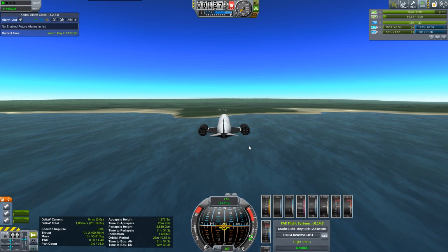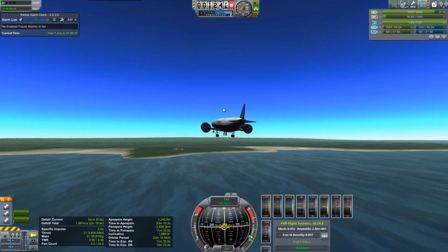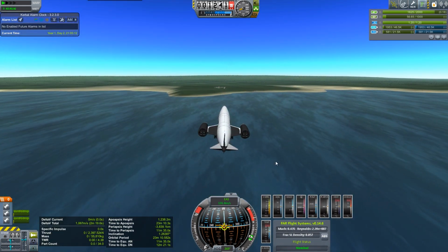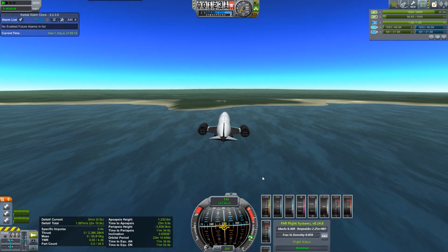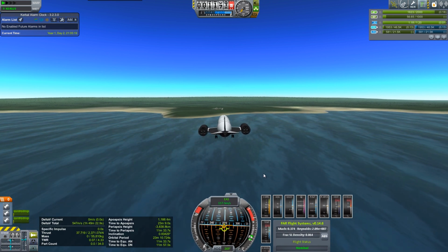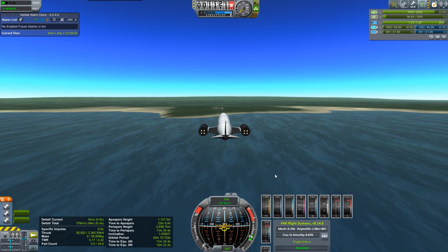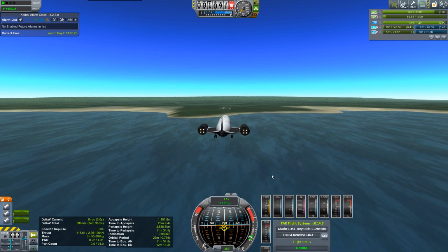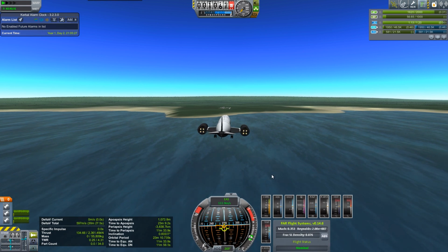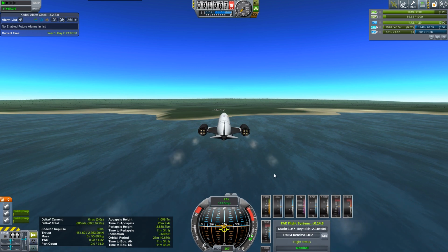Good, and let's stick that gear out. There's some landing gear. You can see our airspeed dropping dramatically with all that drag. So let's add a little bit of power and more pitch trim back. Okay, a little bit more power, please. Let's not be slowing this much. The engines don't spool up just immediately. Takes them a little bit. Okay.